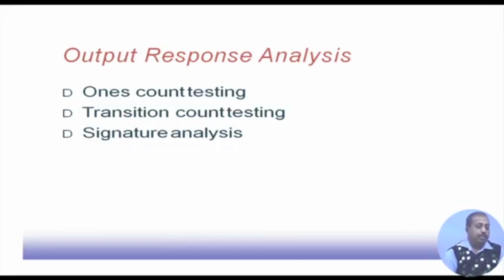Next, after the pattern generator, the next important module that we have in BIST testing is the response analyzer. This response analyzer may do many things. On the application of every pattern generated by the pattern generator, some response is generated. Now, we cannot store all those responses in the circuit itself, because the pattern generator was running in an autonomous mode, generating patterns and applying them to the circuit, but the responses cannot be stored, because that would be huge, for the sake of comparison.